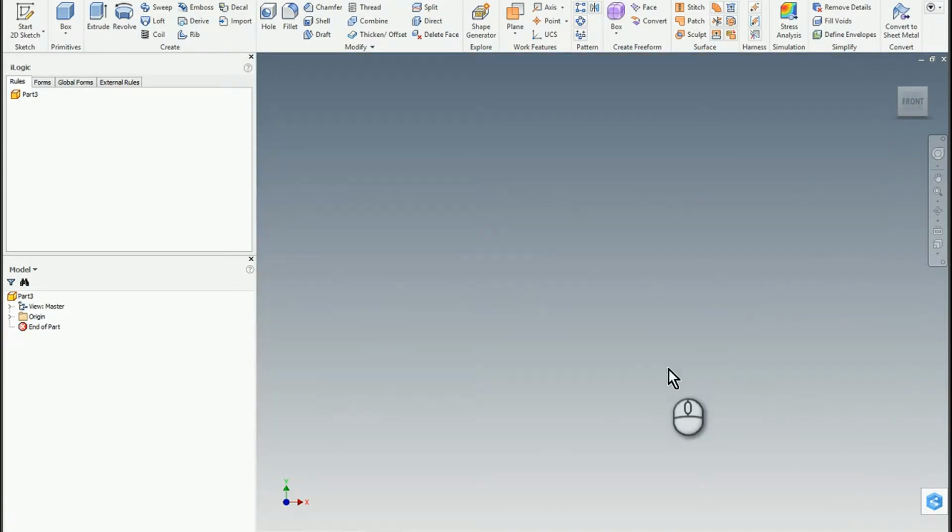So go ahead and hit done. And now because this is factory, the z-axis is actually always up. So what I recommend doing is either making a template ahead of time or coming into your view cube, clicking on the front face, and set that as top. And then what I'll also do is I'll set up this orientation and I'll set this current view as home. So what I'm doing there is now I'm setting it up so that I understand, oh yeah, I'm working on a factory asset.